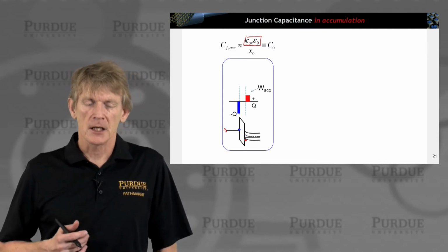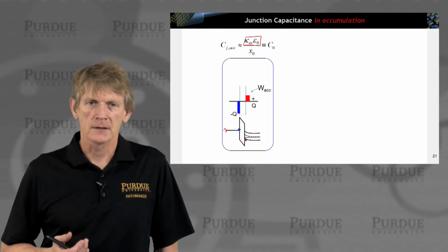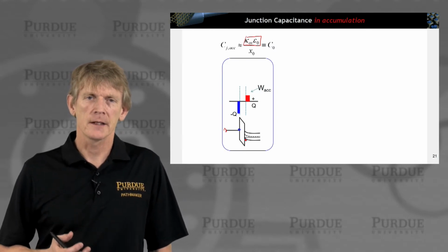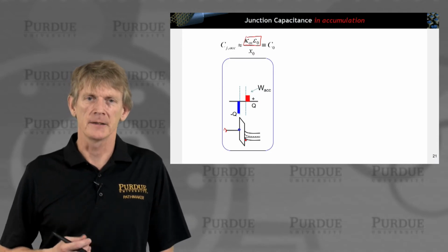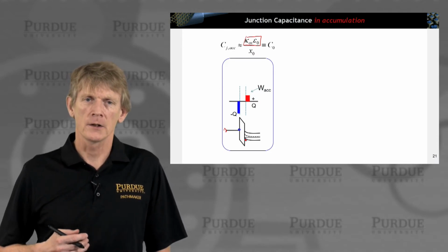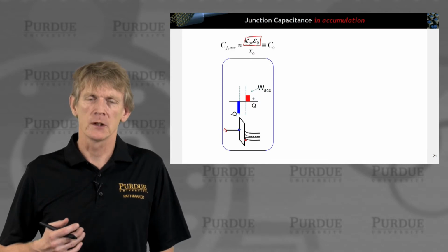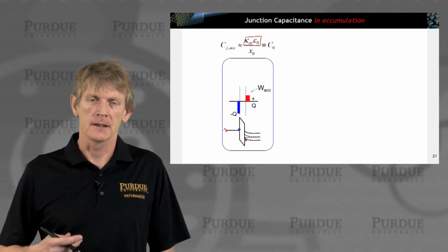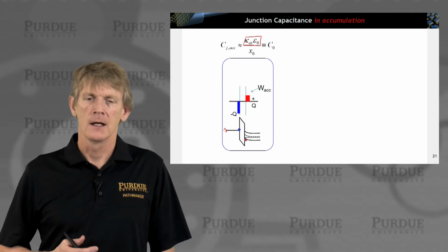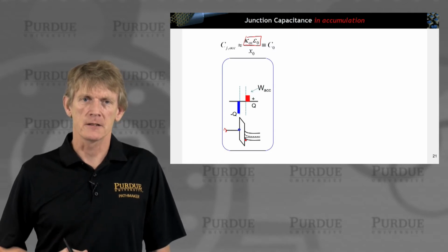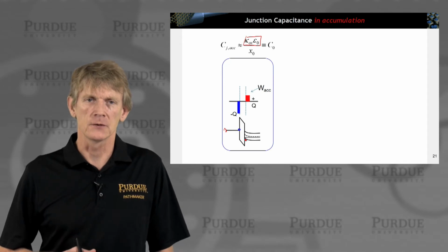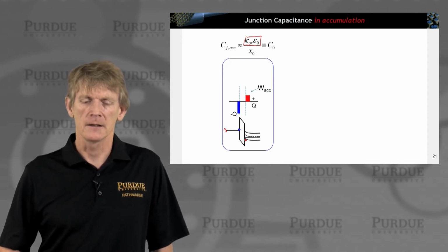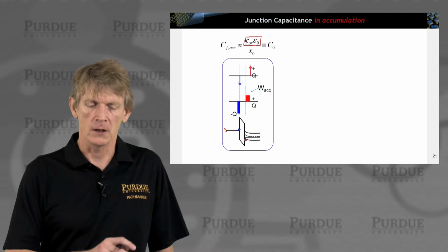Now, the charge in the semiconductor is not perfectly a sheet charge. It has a spatial distribution. There is some band bending that one ought to account for, and that will lead to some non-ideality, in that you don't have a charge that is truly a sheet charge, like at a metal surface, where you assume it's virtually infinitesimally small.